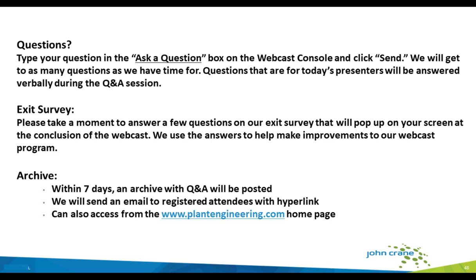Thanks, Brian. Jack, final question for you today. What is the laser face seal pressure limit? Good question again. The laser face seal limit all depends on the actual seal that the laser face technology is added to. Normal seals, the API 682, 41 bar, the seal is actually handling that. However, we do have seals like the 8600 seal. It's running at 200 bar plus. So the pressure limit is actually dependent on the actual seal that the technology is added to the face.